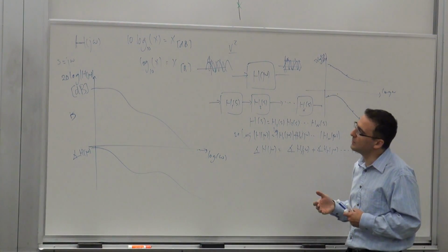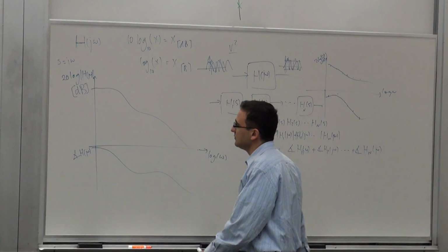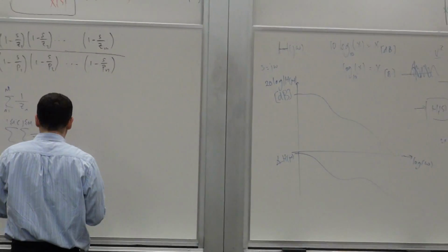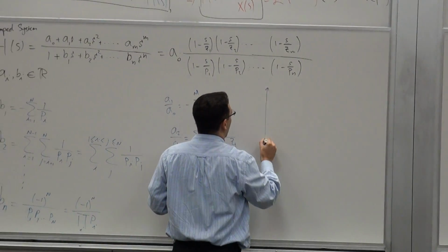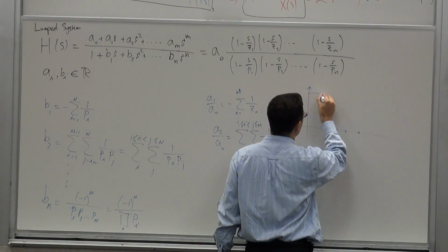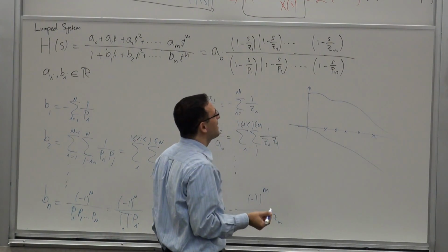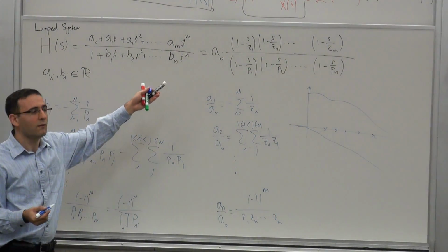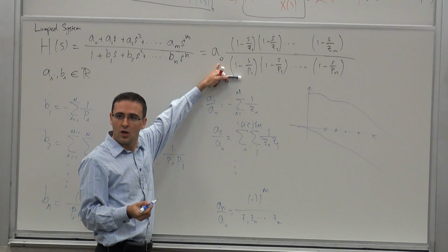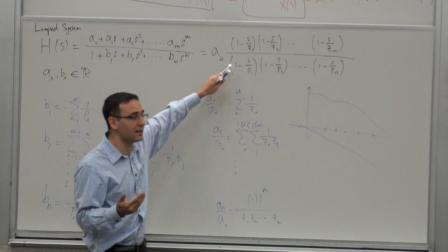So anyway, we do a lot of Bode plots to determine things. And on a Bode plot, a transfer function like this would have the following form. So you have poles and zeros, and then you have some transfer function that looks like that. The bottom line is that this form is very suitable for where you have a DC gain like that. Correct? Because if you have a constant, well-defined DC gain, then this is a good form to write it.